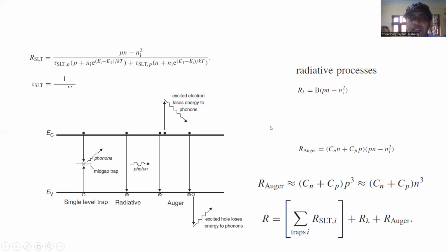However, radiative recombination doesn't occur in the same direction as the incident radiation, and it is random in direction. So some of the re-emitted photons can be lost. So we should try to minimize all kinds of recombination processes, but specifically we should try to decrease the non-radiative recombination rates in these devices.